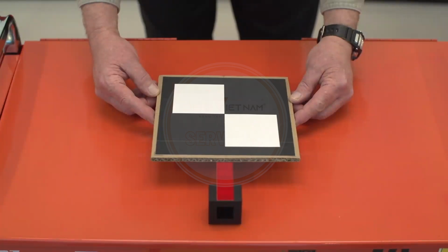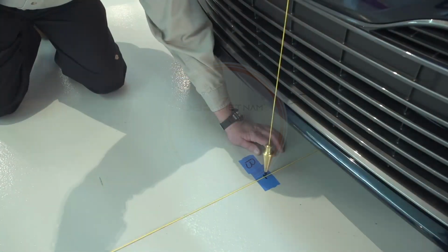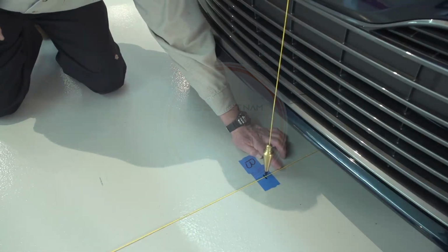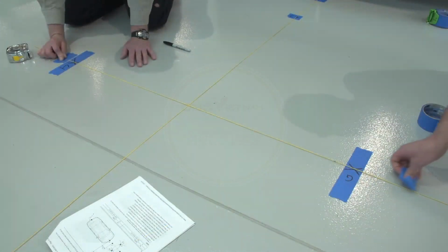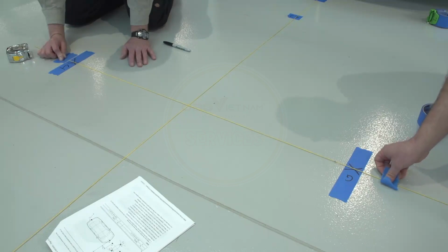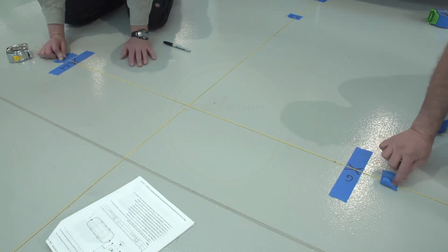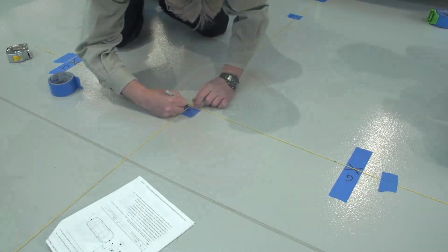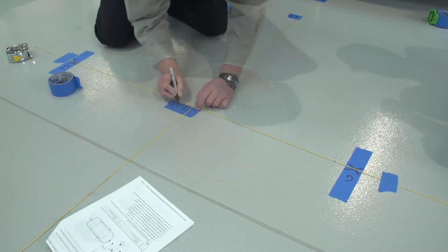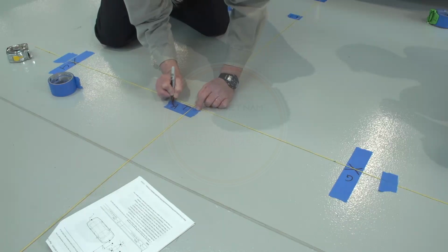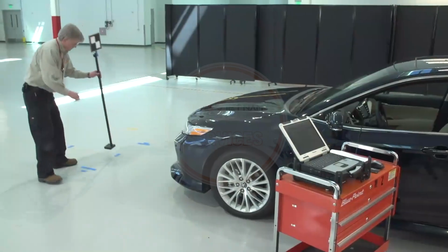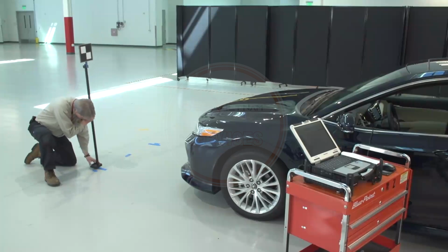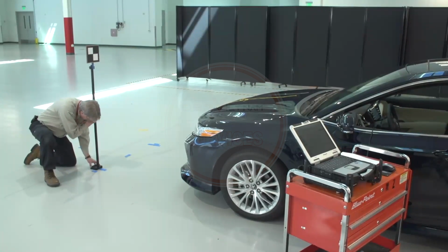An overview of the FRC adjustment procedure includes: secure an appropriate area for performing the adjustment. Make a high contrast target of the correct size and shape. Create a vehicle center line projected in the front of the car. Make a line at 90 degrees perpendicular to the center line at a specific distance in front of the car. Mark 3 target positions on the center line and the perpendicular 90-degree line. Place the target at the specified positions and use the Techstream to perform the adjustment procedure.